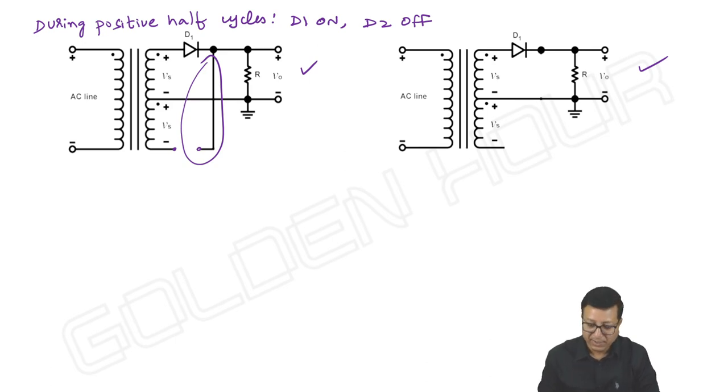Then how does the current flow? Positive to negative terminal of the source. So the current starts here and ends this way. It is flowing through the diode from anode to cathode, downwards, and I can take this current as IL. Then how does the circuit look? It looks like a simple half wave rectifier, is it not so? Taking the secondary coil internal resistance into consideration, I can write IL is equal to Vs by Rs plus diode forward resistance Rf plus the load resistance RL.